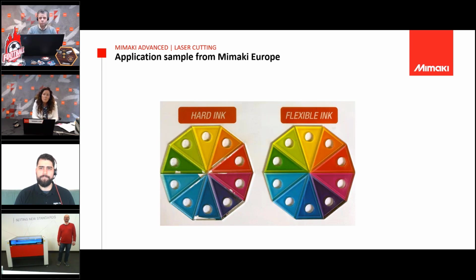I see similar things, especially also the type of substrate makes a big difference. So you cannot just use any acrylic and everything will be good. For extruded acrylic, results are usually fine. For cast acrylic, the results vary. So even if you have the right ink, the cast acrylic has a very smooth surface and your ink will not stick as well. Unless you use some primer, and then you get excellent results as well.